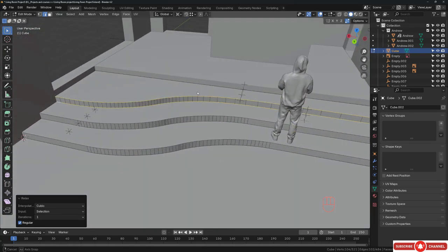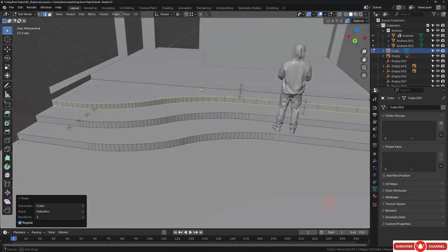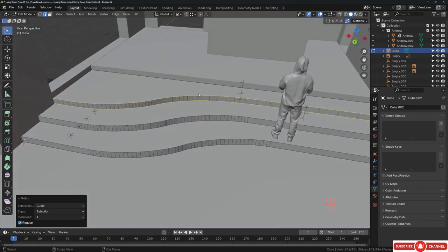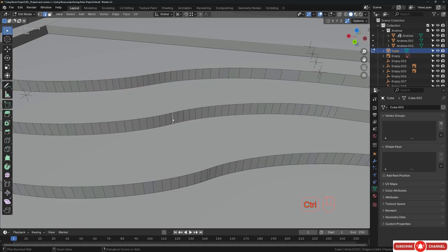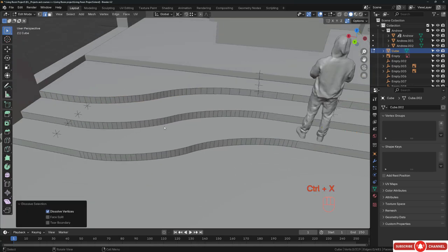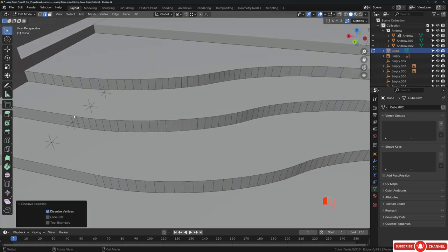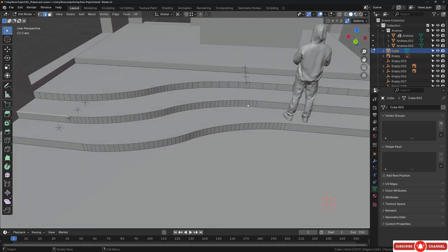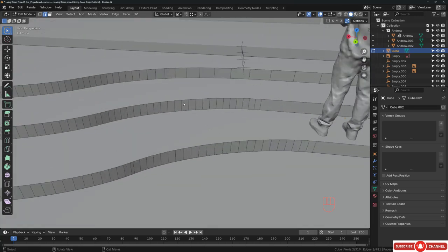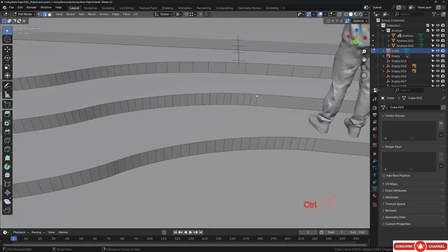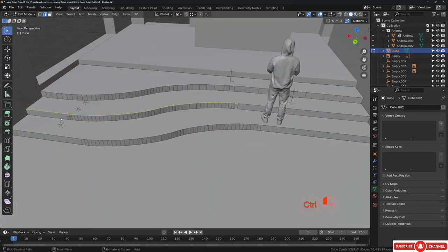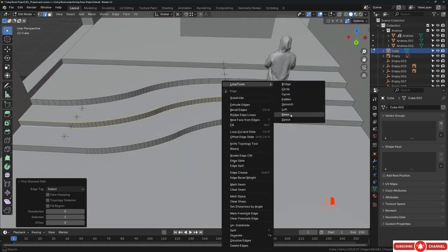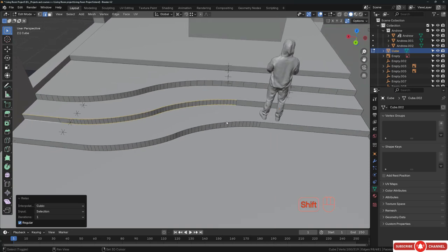All right, now it's become smoother, as you can see. All right, I will do the same thing for this one, but I will delete this closed edge. I don't want it. And let's try to select the edges starting from here and ending here. Let's see if that will make any difference. Right click, relax, hold Shift R to repeat this again and again.